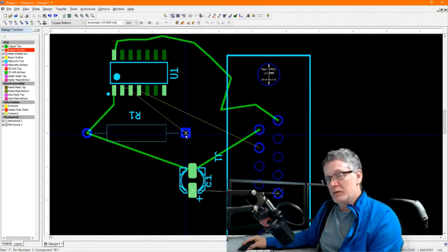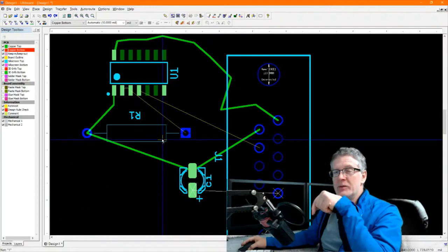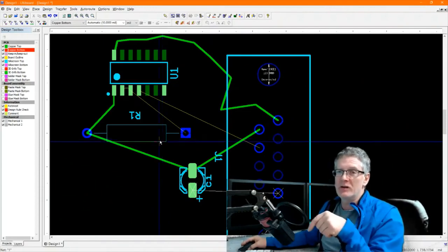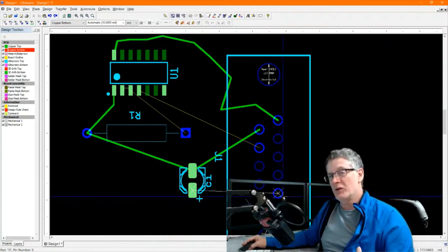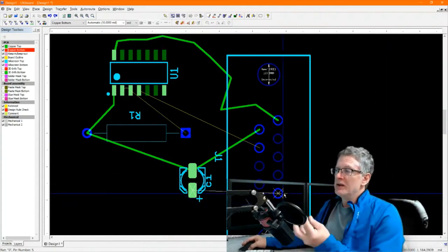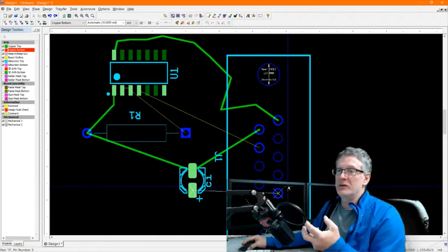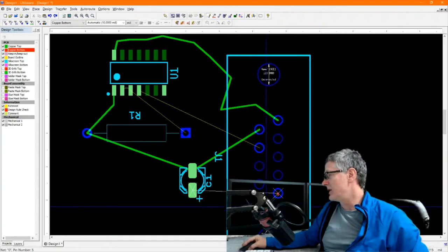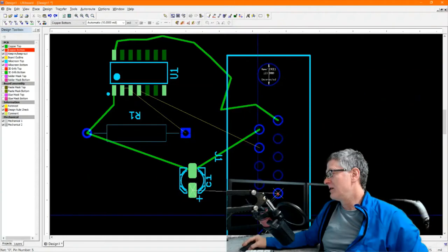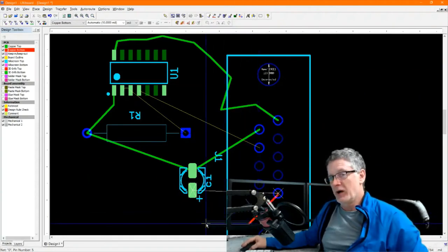The hole on a component has a tiny piece of copper plated into the inside of the hole, so it is conductive through the hole. When you solder these parts to the circuit board, the hole fills with solder, and you get a pretty good connection through it that can take a fair bit of current. So I'm going to start routing a trace from here on the red side of the board, which is the bottom side of the board.